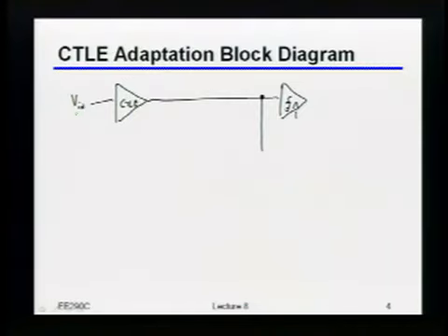It's basically an FFT engine, but just a 2-point FFT. Oh, okay. You could actually do an FFT. By the way, remember I want simple and low power. So I think I need the ADC and the FFT. So I guess you're right, a 2-point FFT is not so bad, but I think I can do it with less overhead than that. But that is indeed correct. Well, there's another minor caveat, which is my signals aren't guaranteed to be periodic, but we'll ignore that too.